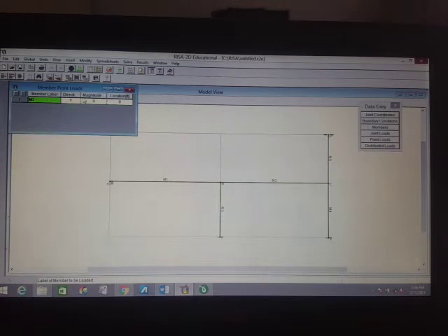And then what's the direction? There's a vertical load, so that's the y direction. Then the magnitude, since it's downward, is negative 32. And the location: we're actually given a dimension of 20 feet, but the location of the point load is just 10 feet from this point C. So even if our reference point is B, that's going to be 10 feet. Meaning the location corresponds to the location relative to this member.